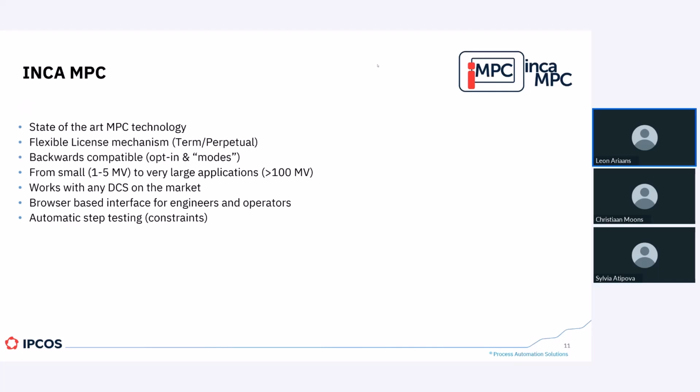And also, when you are doing maintenance to an MPC, you already have what's probably a pretty accurate model in place already. So then switching to stepping mode to collect further data to improve your model after a while, that's also something where automatic stepping can help you with.